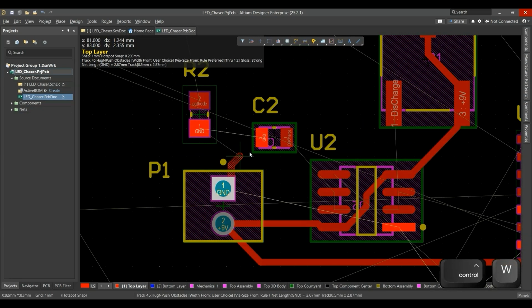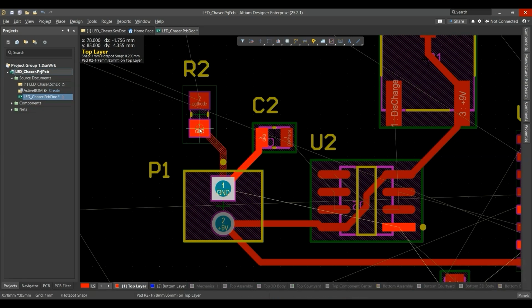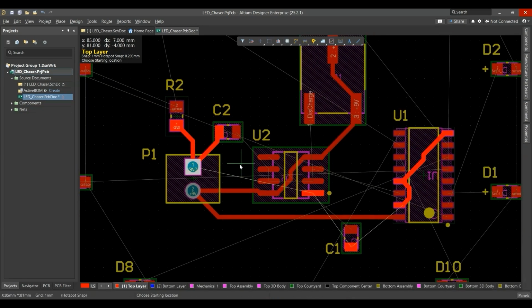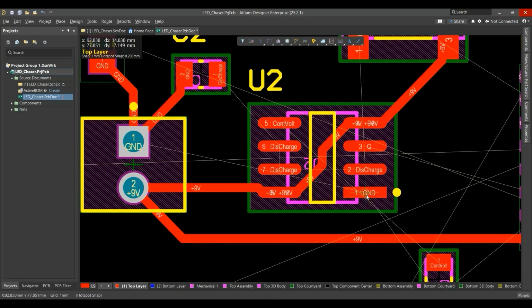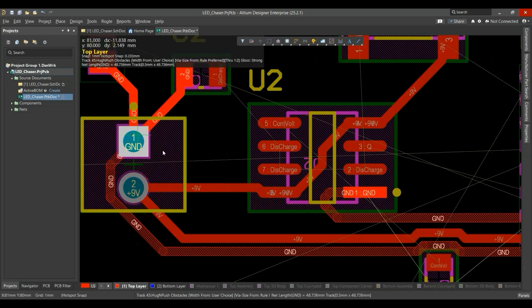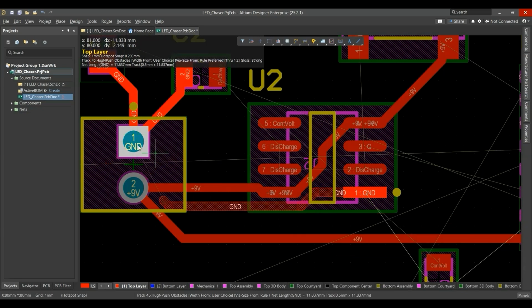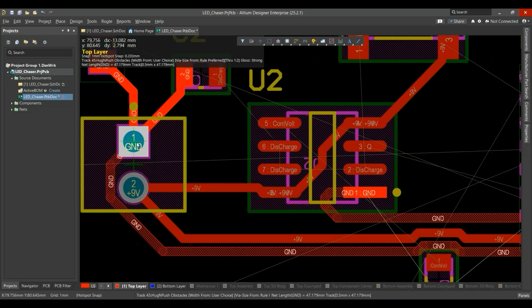And selecting the paths, Altium Designer software shows you where this path must be connected to with the use of lights. As you can see, here I want to connect a GND of the timer to GND pin of the header. There is no straight way to do that. And if there is one, it needs to take a long turn, which is not logical.